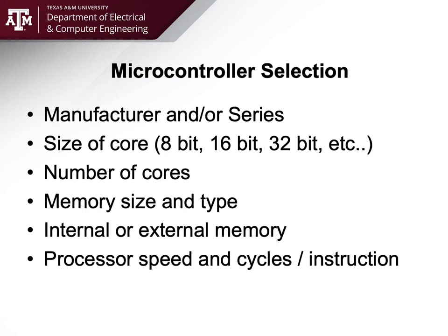So literally, if you want to have fun, type microcontroller DigiKey and see the tens of thousands of microcontroller types, not even quantity of parts, but different species of microcontrollers there are. So use the specs that you've determined to drive this. Do not allow the microcontroller to drive your specs. I have done that in the past. That's where you end up wasting weeks of your time. If you let your specs drive your microcontroller, you will end up with the right one.